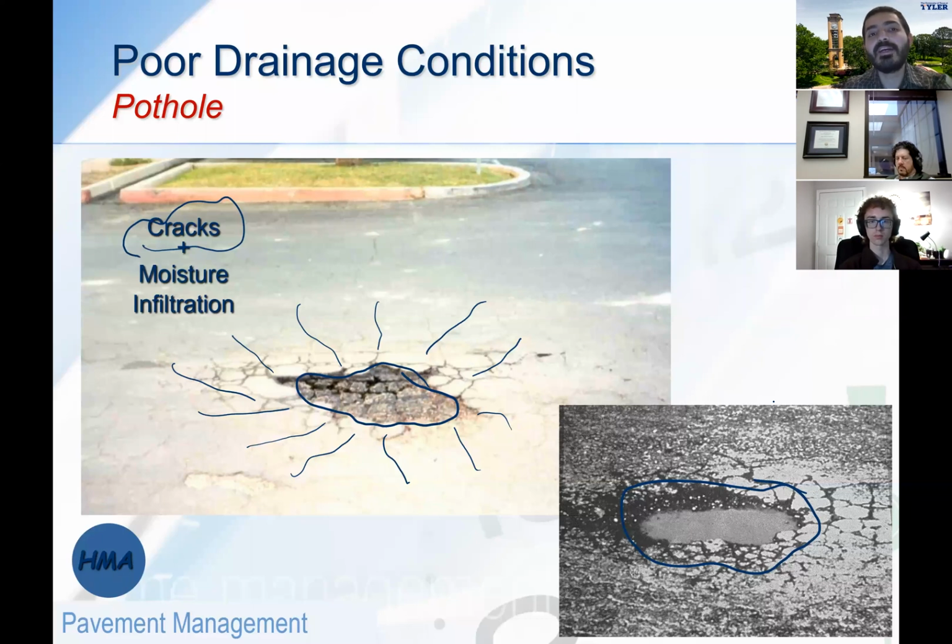Sometimes we also end up making those without realizing, by taking a core. If you're going to the field trying to observe what the problem is, you take a core, and if that core is not filled very well, that is a weak point that you're already creating in the structure. If it's not compacted very well, again, it's a weak point because it's fill material that's not 100% homogeneous with the rest of the structure, and if it has higher air voids, the water will get in there.